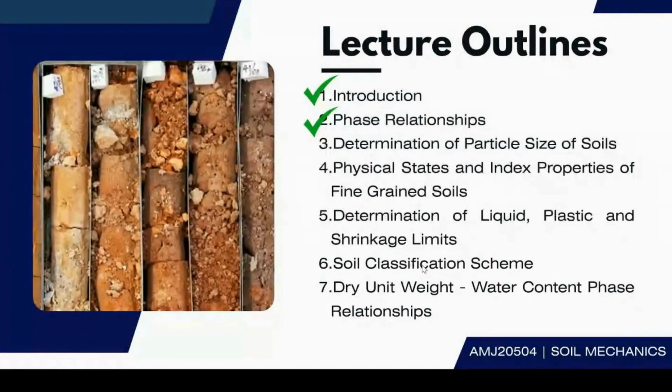If you don't have the weight, the moisture content, the unit weight, the density, you cannot determine the soil bearing capacity. Because based on the soil bearing capacity, you will determine the stress and the strain. How to get the stress and the strain comes from these basic values, from the phase relationships. So they are all related. Alright.